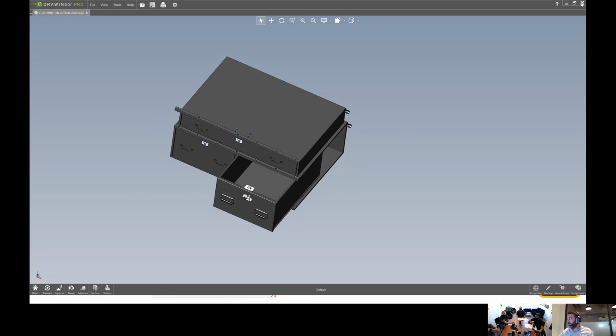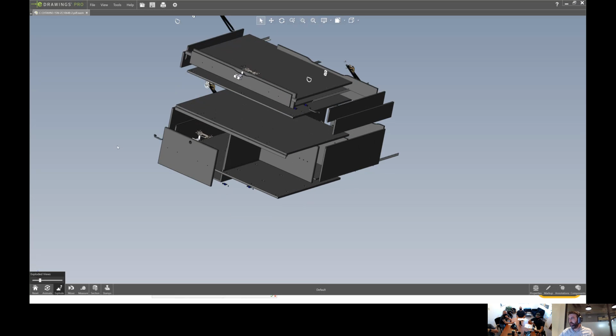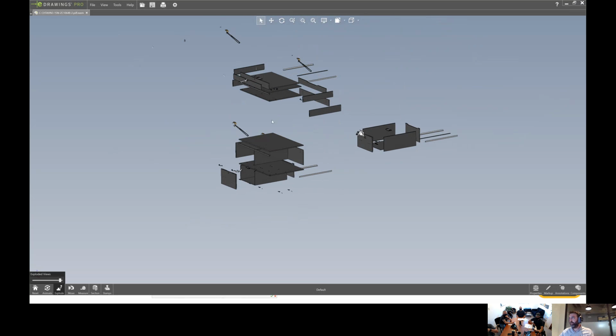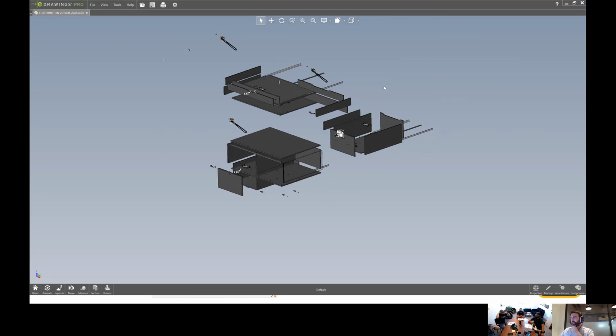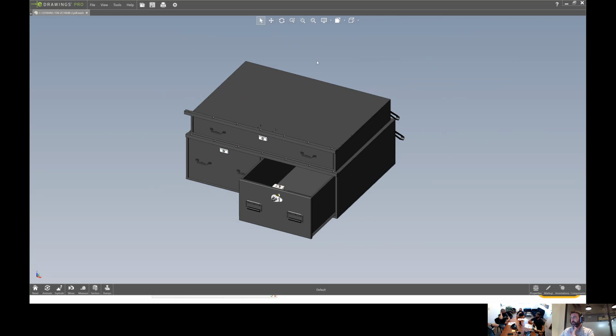Can you predefine exploded views in this environment? Here you got one by default. And after, I think it's going to use the one you create in SolidWorks, if you have one inside SolidWorks. But you need to create one in SolidWorks first. Yeah, the default one isn't helpful. We would have to create a version in SolidWorks. If you create it while you're building it, it will show up in here. Is that what you're asking?